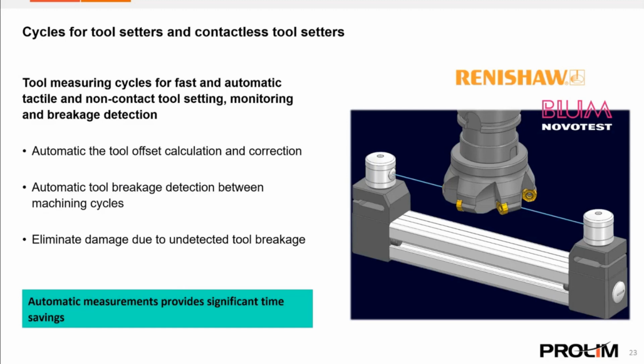This expands the ability to measure the cutting tool geometry directly on the machine tool, where you can check the wear and respond to the deviations. This can be a valuable saving for low-manned operations. You can always trust the laser beam tool setters or the other tool setters. Whenever you have a tool breakdown, it will give you an alarm, and the machine can be stopped to change the tools.